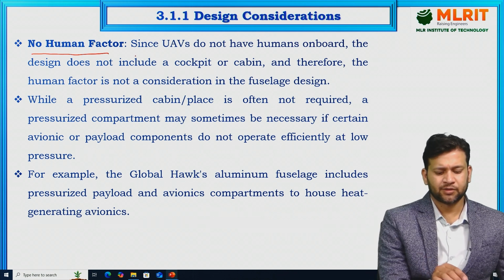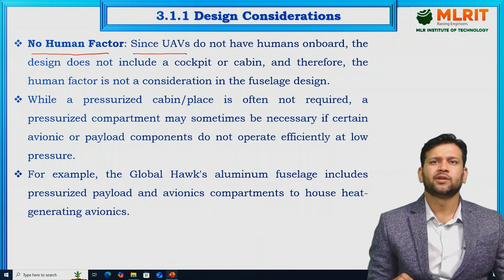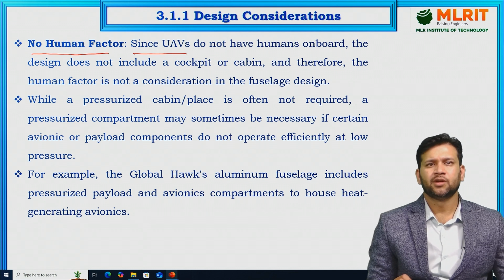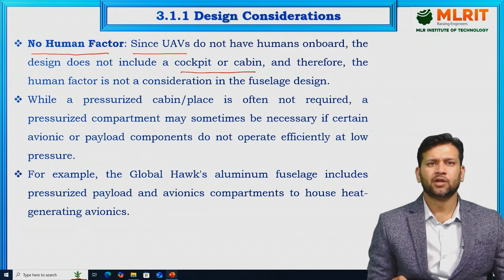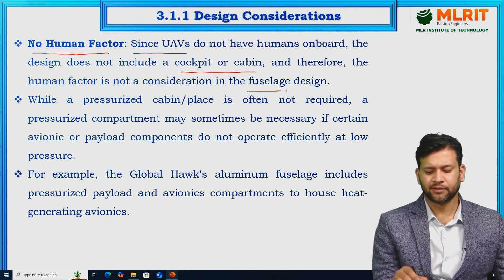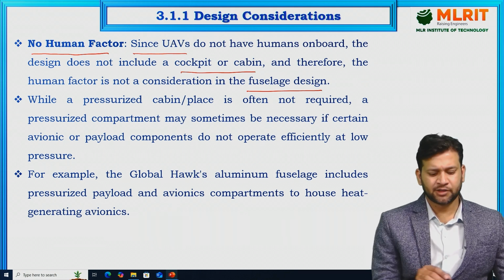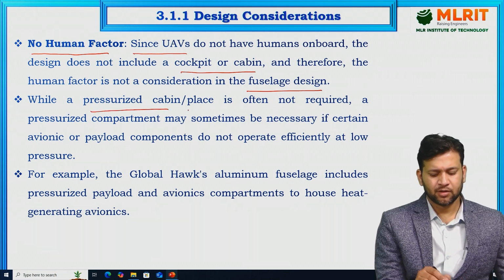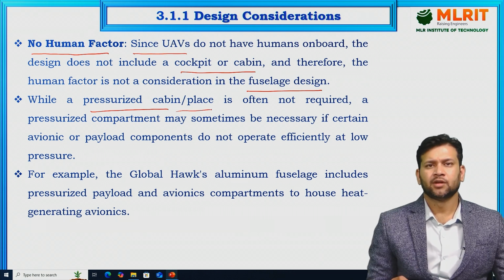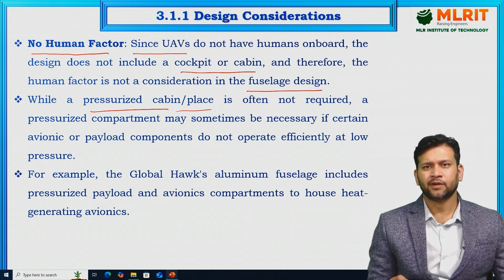So since UAVs do not have humans on board, the design does not include a cockpit or cabin, and therefore the human factor is not a consideration in the fuselage design. While a pressurized cabin is placed in most conventional aircraft, in an unmanned air vehicle it is often not required.